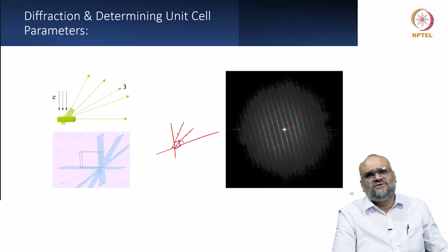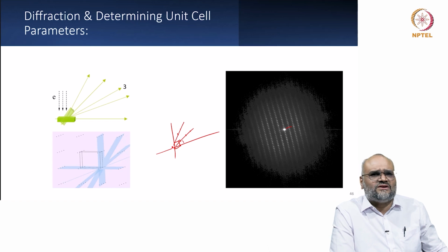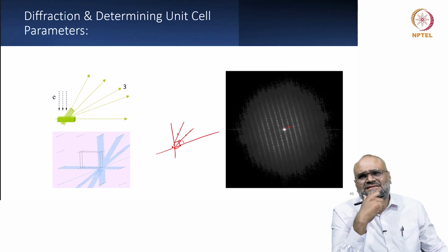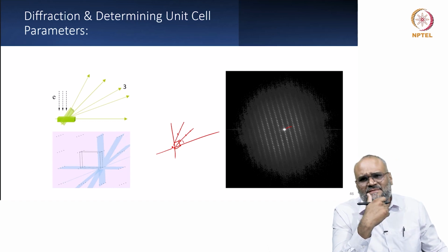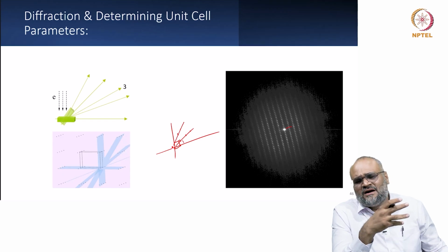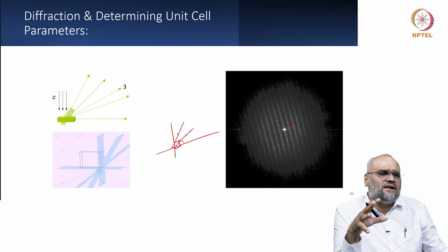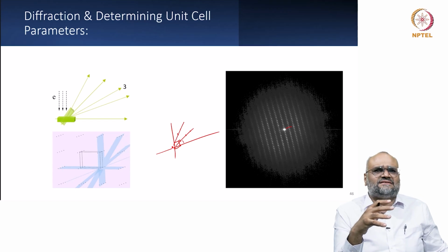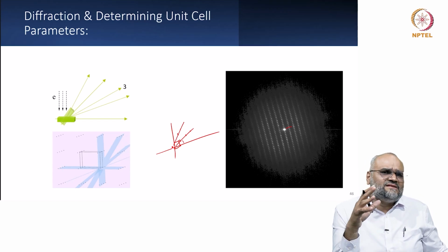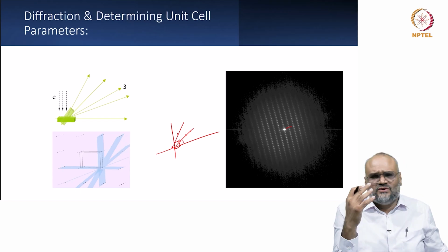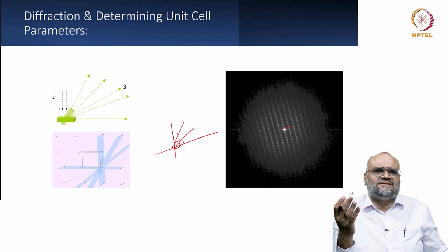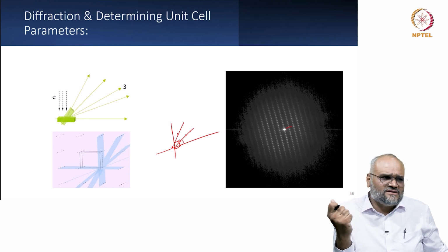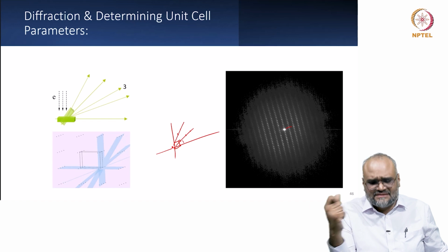So this helps you determine the unit cell parameters very accurately, and once you know this, you can also get information on the symmetry either by corresponding X-ray diffraction pattern and by using Rietveld refinement methods, or by using convergent beam electron diffraction techniques and determine the symmetry, and then you would have solved the crystal structure to an extent. And then once you determine the space group, through focus exit wave reconstruction imaging by high resolution electron microscopy, you can completely solve the crystal structure.